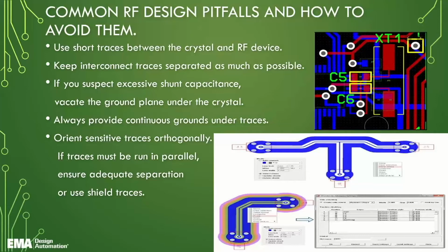The diagram in the bottom left shows the shielding of RF connectors. The software will automatically go in, identify that trace, and create that shielding for you. The software also will go in and fill that shielding in with the RF ground vias.